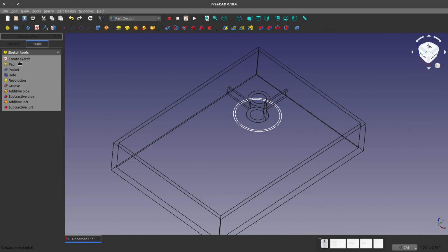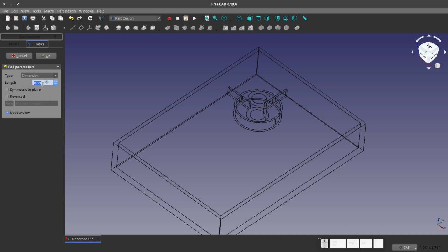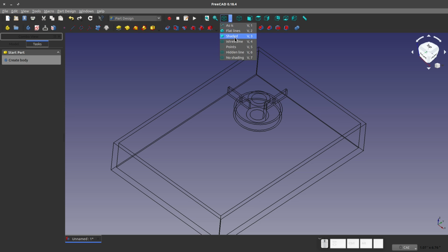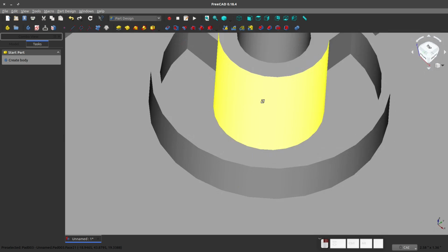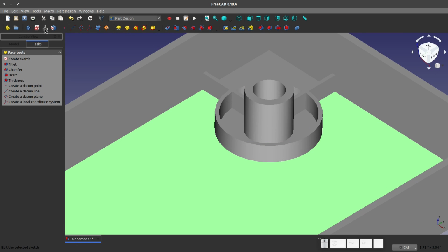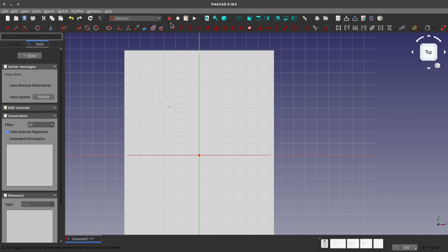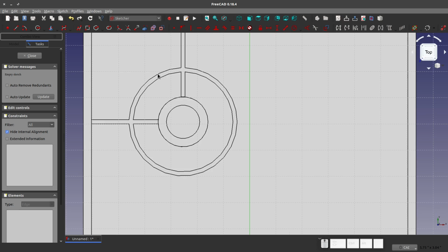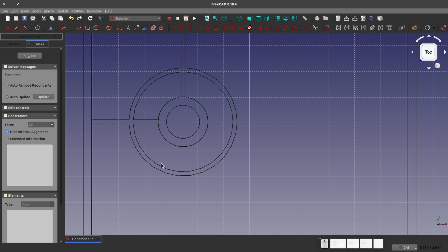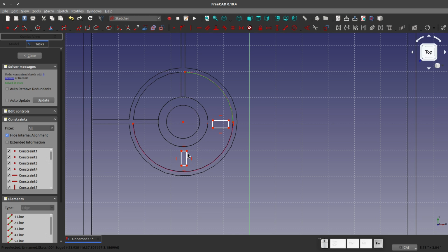And we can extrude that. And we'll do the same, 0.125 times 2.5. Going back to our shaded view, everything looks pretty good. Let's choose this face to sketch on again, and I'd like to add just a few more features. So we'll go back to wireframe. I'm going to use my edge import and import here, here, and we already have our circle center. So we'll just continue on these ribs on the other side of this boss. And actually I'd like to import this edge for some relations.